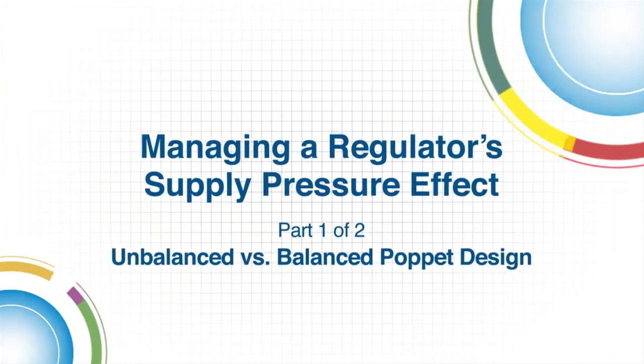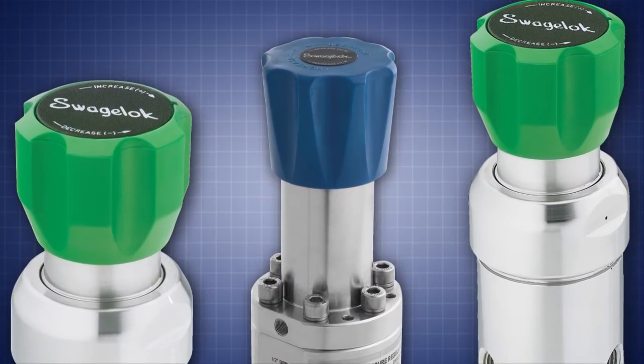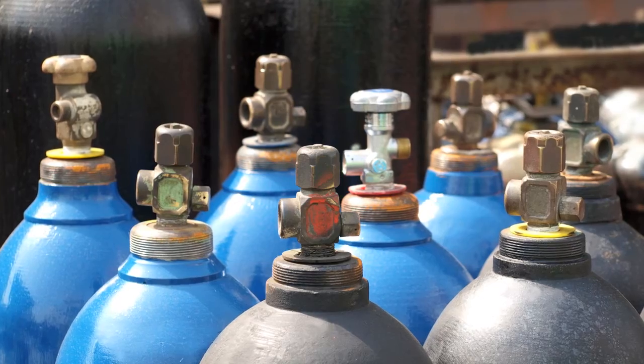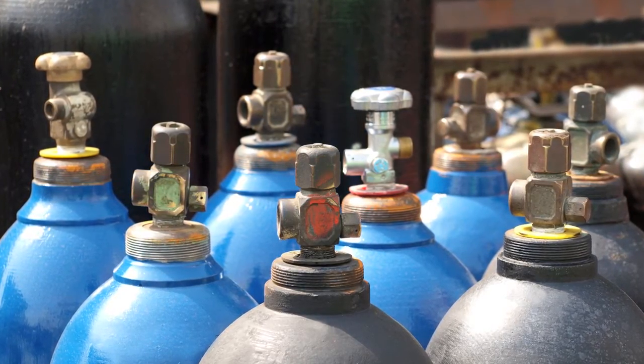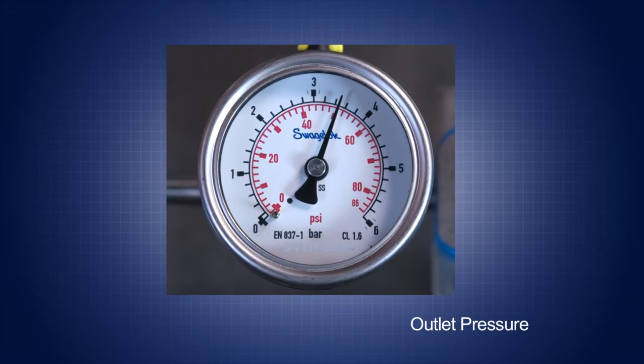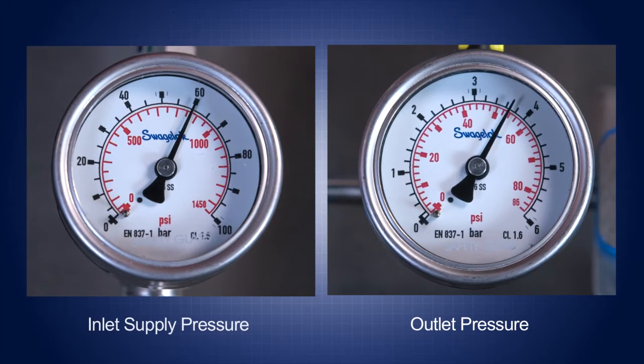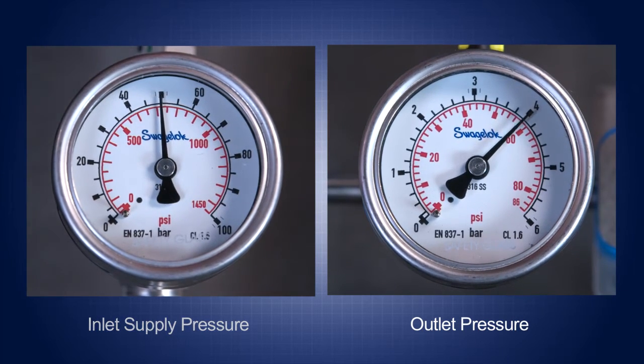Today's topic is considerations in managing the supply pressure effect of a regulator. System operators running a process from a gas cylinder source sometimes observe the phenomenon of outlet pressure increasing in a pressure-reducing regulator for no apparent reason. As the cylinder drains, the inlet pressure to the regulator decreases. You might expect the outlet pressure to also decrease, but in fact, the outlet pressure rises.